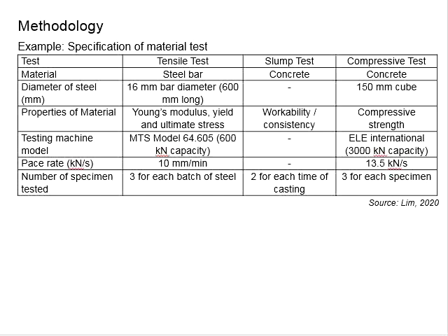Normally, we would like to have some tolerance in terms of the maximum capacity achievable by the testing machine. We barely use the machines towards 100% of their capacity. Although you know that you actually can use the machines to 100% capacity, because normally this kind of machine designed to the intended capacity has its own factor of safety. Even though the sample strength slightly exceeds the capacity of the machine, it will not break, only that it is not recommended in order to prevent any possible damage to the machine.